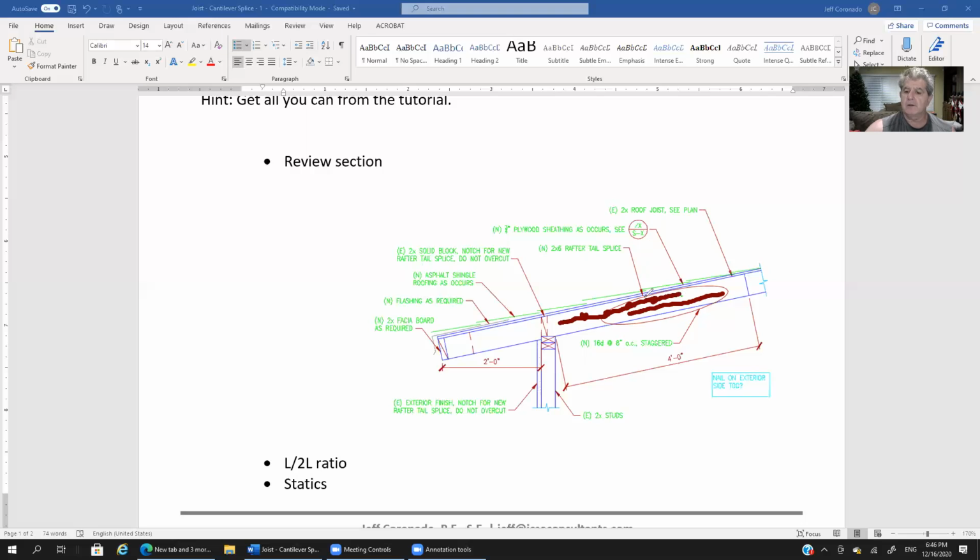So what I've drawn here is not a split, right? It's just a fiber. But if you put several nails in close proximity into the same fiber or between, let's say, the same two fibers, you might create a split. So that's why we would stagger those nails. Okay, so that makes sense.